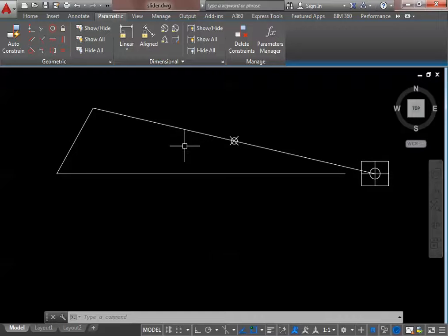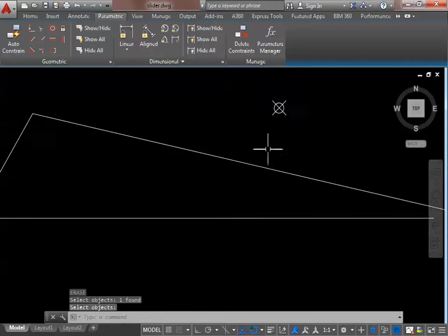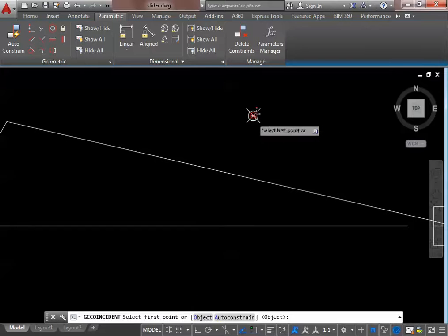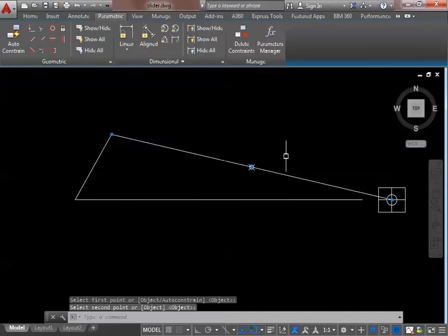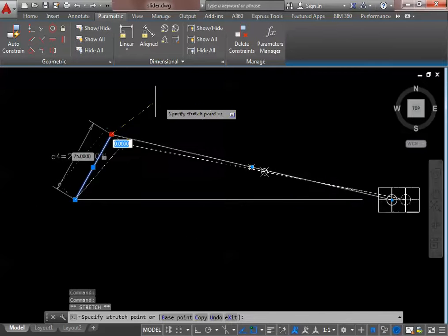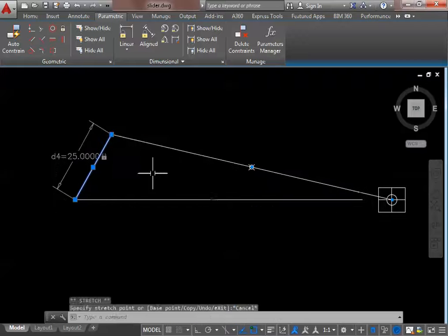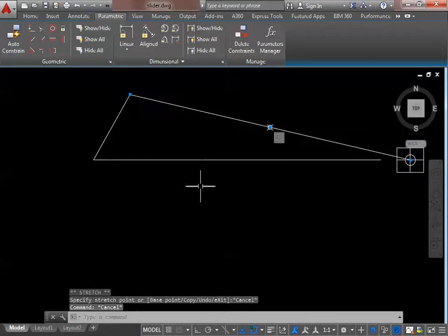So how AutoCAD can help here? See, let us put this point first at the midpoint. So again I need to give constraint. This should be here. Now let us check if that point is moving with this. Now AutoCAD still doesn't have any option which will automatically trace the curve, which is possible with Creo, but AutoCAD,